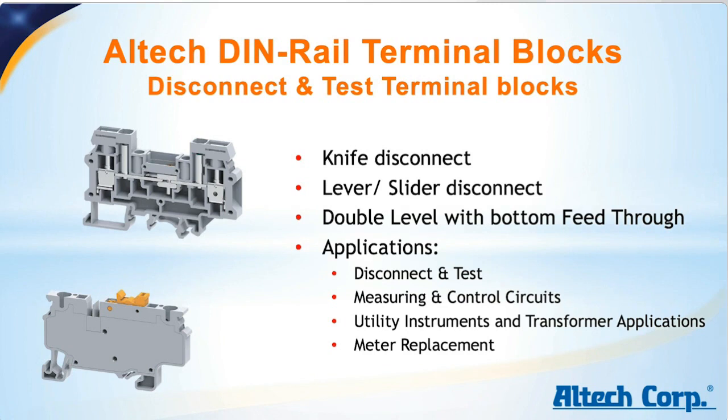Those disconnect and test terminal blocks are an easy solution to enable circuits to be opened and cut from the power source without having to shut off the complete power system. Sometimes they need to be disconnected for maintenance or other test and measurement requirements.